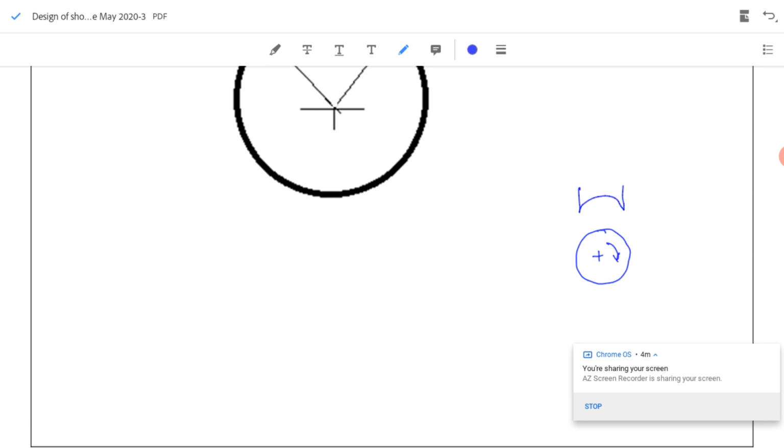I am drawing the free body diagram, so I am separating the shoe with the lever from the drum. Here we have the fulcrum. When we apply force P, the shoe will move downwards, or it will exert a downward force, that is the normal force Fn. Drum is rotating clockwise, so the friction force should be opposite to motion, that is Ft opposite to motion. On the same point on the shoe, Fn will be acting upward direction and Ft will be acting towards right.